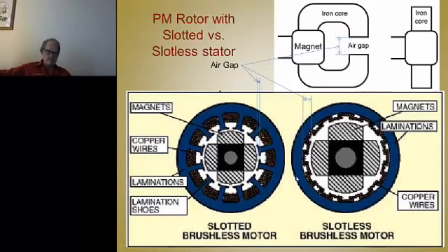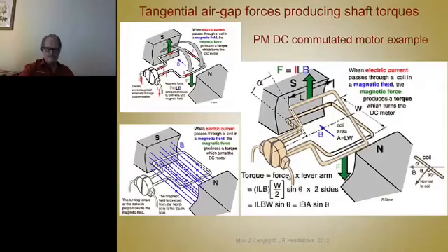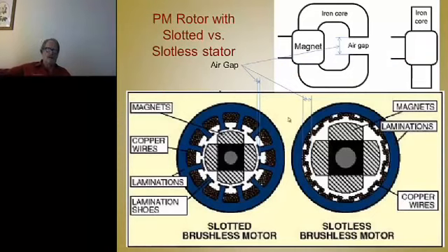You see it there? Now our air gap goes from the OD of the magnet to the ID of the stator core, same as it went from here to the tooth. Now the conductors are really in the air. They're right in the air gap. So now we can readily see that the data of the previous slide applies to this directly. Here our magnetic field, B, goes from north to south here. So there's a force created on that.